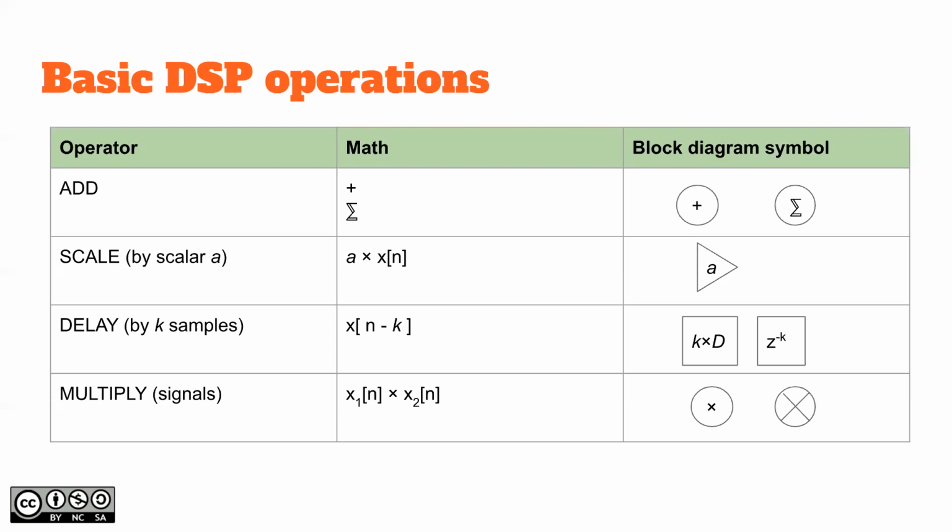And then if you are also dealing with other systems, sometimes you also need to multiply the signals. Signal multiply means mixing the signals, the same as in radio technology, where you have the modulation. One of these signals would be the modulating sinusoid, and another one would be the signal which is sent out.